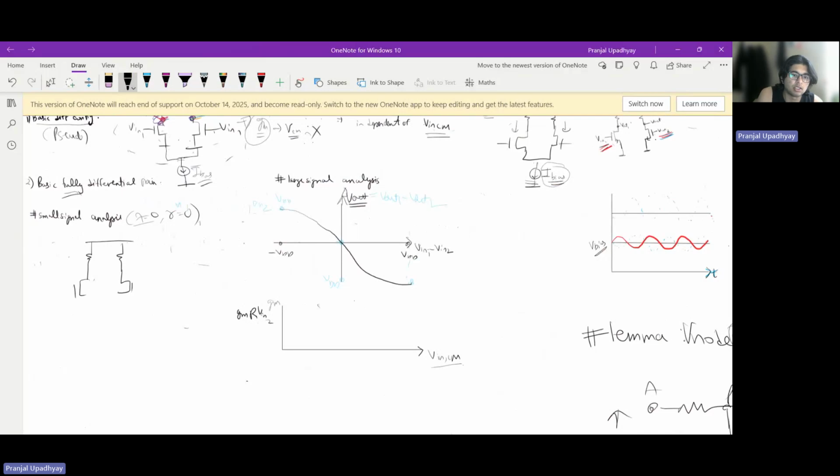And since it is the incremental model, you know that the current source at the bottom will be open, right? So this is what we'll observe. And again, since here it is the incremental model, which means we can apply superposition. So what we'll do is we'll apply one input at a time and try to see what our output is. Okay. So let us try to find what is Vout1 due to first this input and then due to this input. Okay.